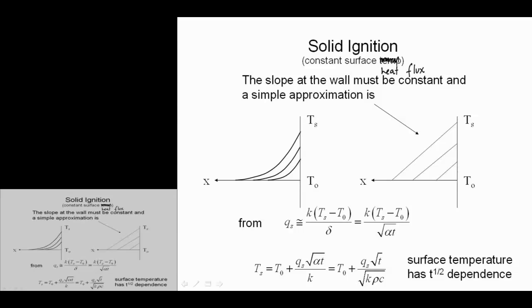So when we look at a constant surface heat flux problem, this is a case where we have Q external on some surface. This is the in-depth profile. One thing that we have to take into account is if this is really a constant heat flux, then the boundary condition internally is that minus k dT/dx at x equals 0 is specified. That means that if it's a true constant surface heat flux problem, dT/dx is always the same at that interface, and that's what we're showing there.